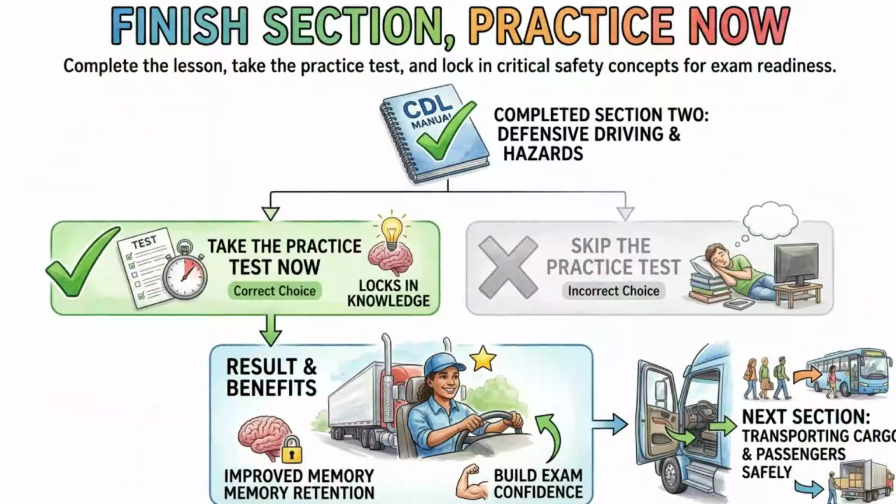Experiencing brake failure on a downgrade is a terrifying situation that requires immediate, calm action. If your brakes fail while descending a mountain, you should look for an escape ramp immediately. Escape ramps are specially designed lanes built with soft gravel or uphill slopes to safely stop runaway vehicles without causing damage or injury. If an escape ramp is not available, you must look for an alternative open area or a side road that goes uphill. You will be tested on the importance of knowing where escape ramps are located on your route.